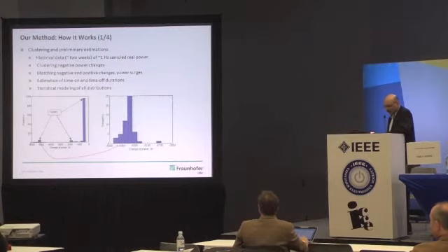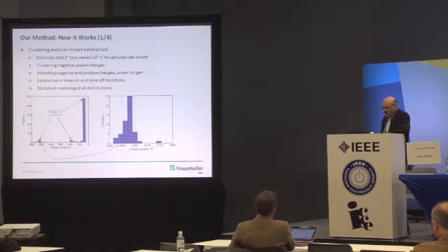Why were you clustering negative power changes? The problem with the positive and negative power changes is that for some appliances there is a power surge. Oh, right, okay. Yeah, this is one thing. Another thing is that several appliances have distinctly different positive and negative power changes. For example, a refrigerator: even if we remove the power spike corresponding to the inrush current, the power draw at positive power change when we turn it on is 5 to 10% larger than when it goes down.